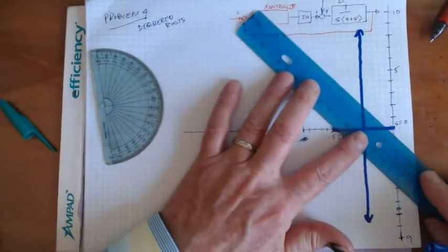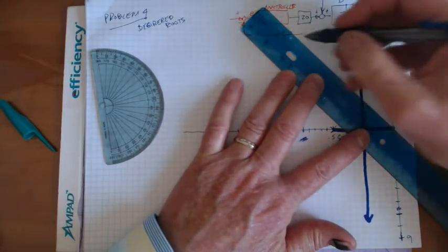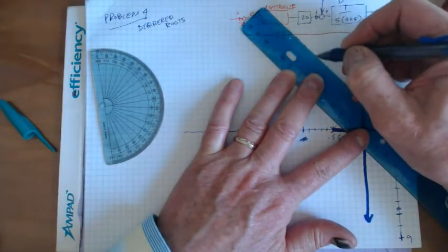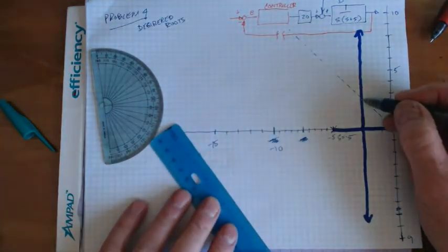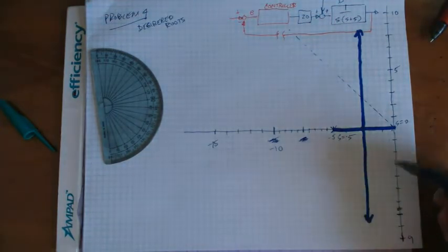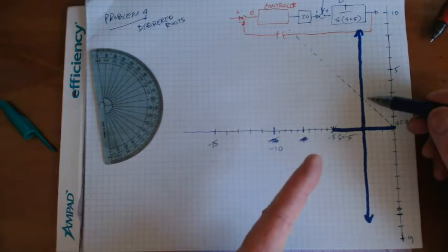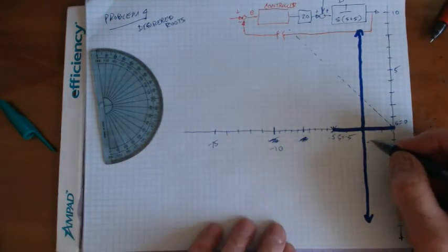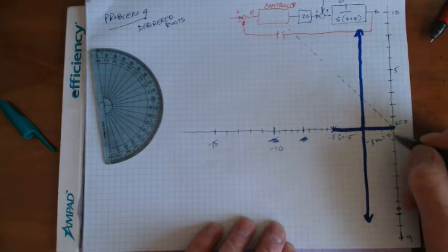I should be able to just do 45 degrees by looking at the corners of my grid here. We could just choose a 45-degree angle if nobody has any other specifications, and say, okay, that's the gain that we need to use. You can use the magnitude criteria to find out what the gain is if you want to. But we can also see that minus zeta omega n is equal to 2.5.